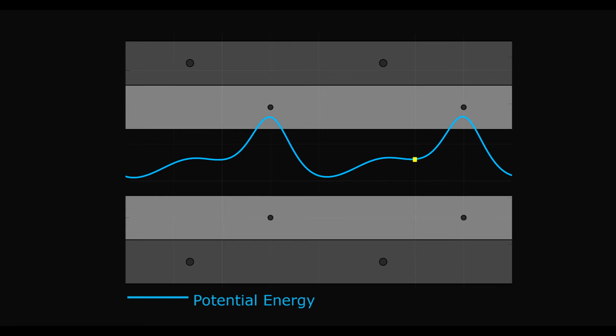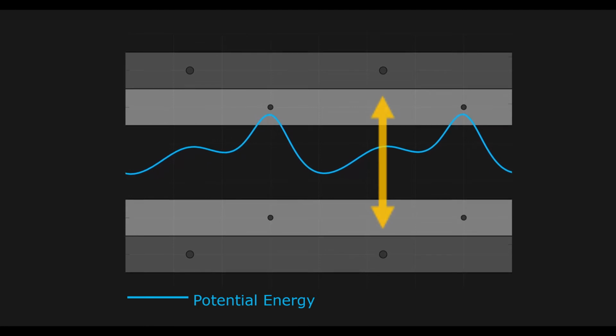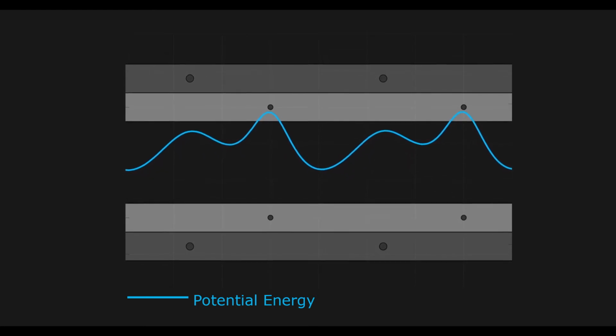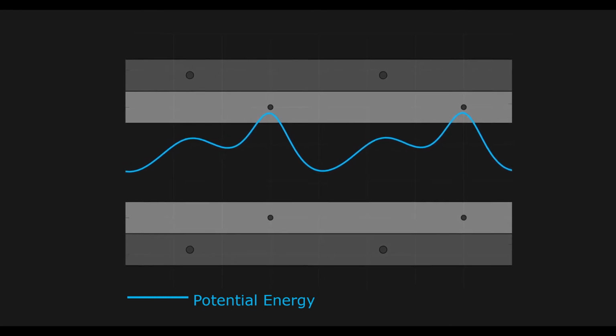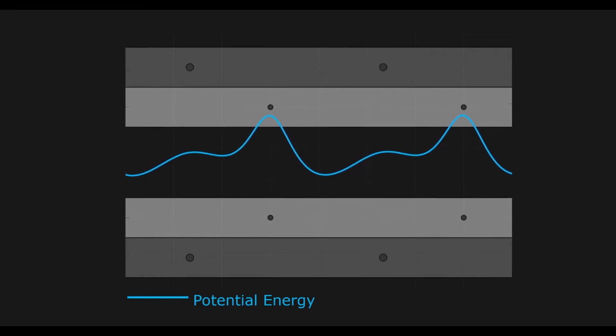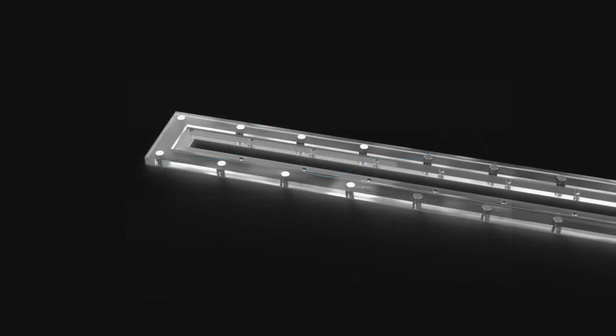This will make it so that pushing an element in the forward direction will take only a small amount of energy, while pushing it in the backward direction will take a lot. Adjusting the vertical spacing of the boundary allows me to change the relative height of each peak. This can make it easier or harder for the disk to change potential wells. To summarize my design, the inside boundary of magnets will be shifted a certain amount to create bistability. Disks will be added to the system so that when energy is added to one of them, the wave can propagate throughout.